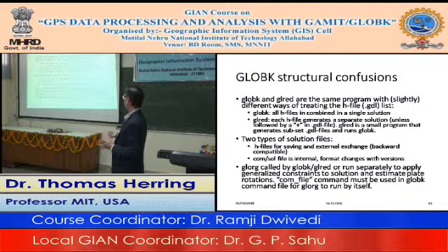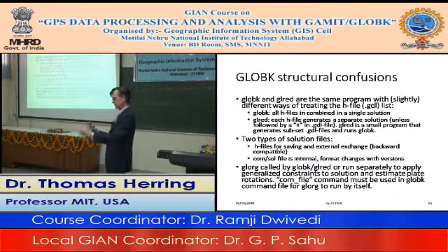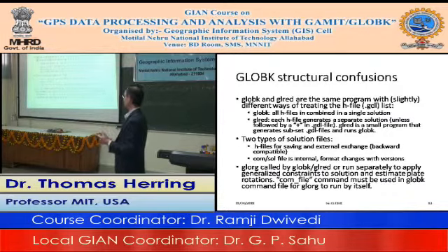GLOBK is called by GLRED, or it can be run separately, as I said. And to run GLOBK by itself, you have to use the command called COM file. By default, that command is not given, because if you're just running a single network at a time, the COM file is quite large, and there's no reason for it to be written out. So it just saves time by not doing it. But if you want to run GLOBK separately, you need to make sure it's set. And you need to have this be a unique name if you're doing multiple different things and you want to keep the solutions separate.